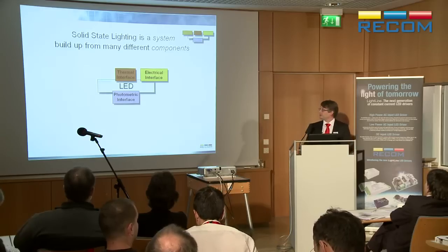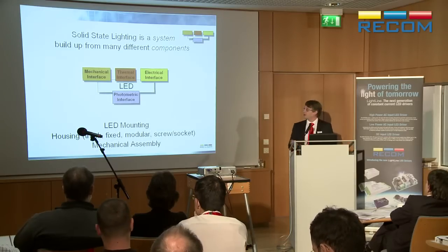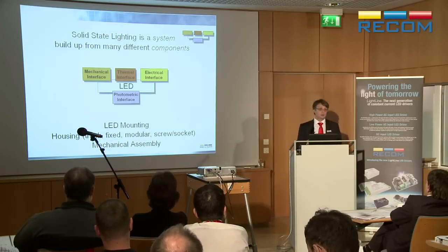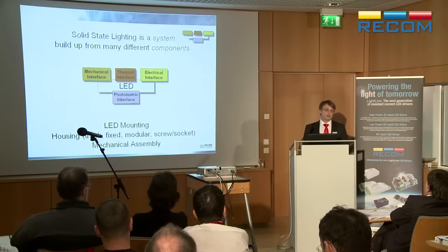But I must stress that this is just the start of the whole process. The mechanical interface is often overlooked. Too often it's done as the very last stage of the design, and it should really be very early on in the design. The LED has to be mounted correctly. If you don't mount it correctly, it'll overheat. If you can't get the heat out of the LED die into your heatsink, it won't work.